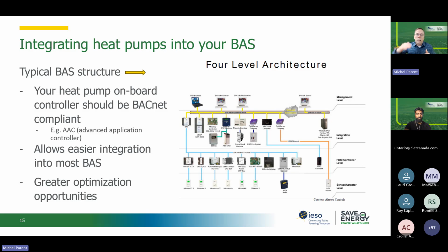So it's really when you want to use a heat pump and you need a higher temperature than a single stage heat pump will be able to provide, which typically would be around 135 to maybe 160, and that's pushing it. Anything higher than that, you will need a specialized heat pump, cascade heat pumps, and you will suffer a COP penalty.